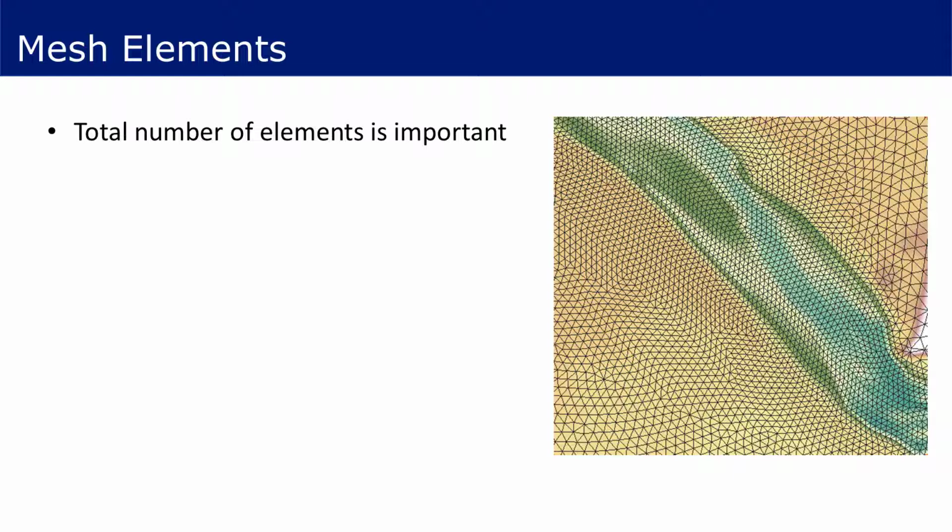As most users are likely already aware from hydraulic modeling, SRH2D model runtimes increase as the number of elements increase. What should be remembered as well is that because of the increased computational tasks, sediment models should be expected to take much longer to execute than a comparable hydraulic model. It is not uncommon for a sediment model to take many hours and even days to complete a run. Depending on the application, these long run times may interfere with the ability to develop the model, iterate alternatives, and analyze results in a timely manner.